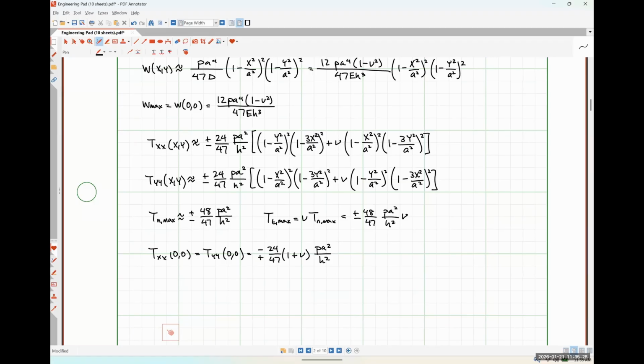So we could integrate piezo resistors onto the surface of the membrane at the location of maximum stress, and that change in resistance can generate an electrical signal, right? So if we apply some bias voltage across our piezo resistors, as that resistance changes, the voltage is going to change across the resistors, and we can relate that to the differential pressure.